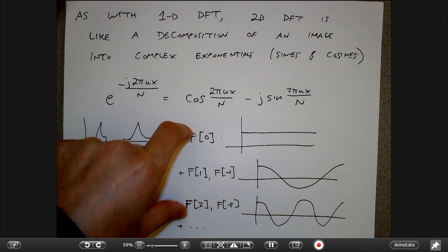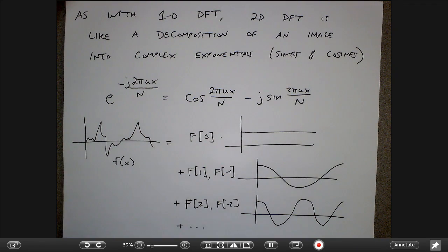Whereas here we're representing the signal in terms of the same number of values, but those values now represent how much contribution there is from each of these sinusoids. So these become the new basis functions for the image. It's like saying how much of this sinusoidal-like image is in my original image. And if I add up those m times m numbers times those basis images, I get back the original image. So it's just a different way of representing the original image.